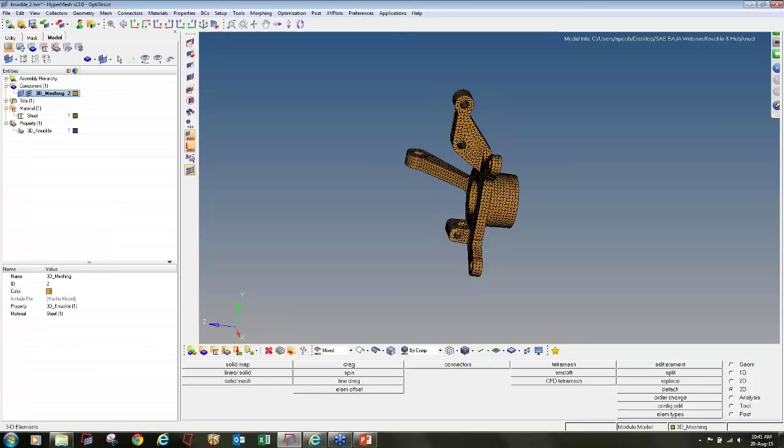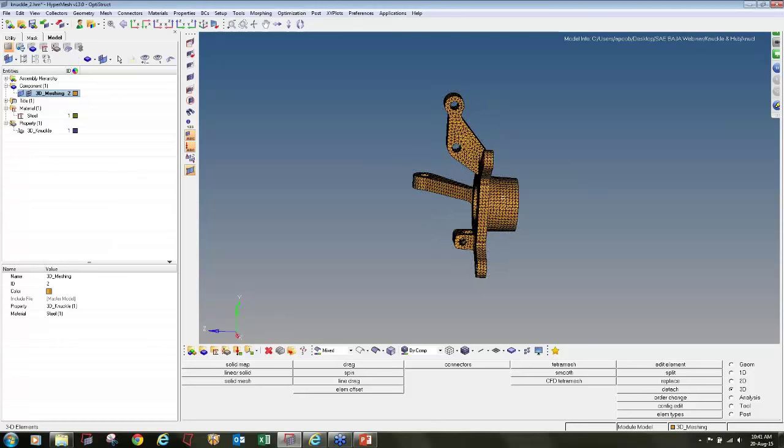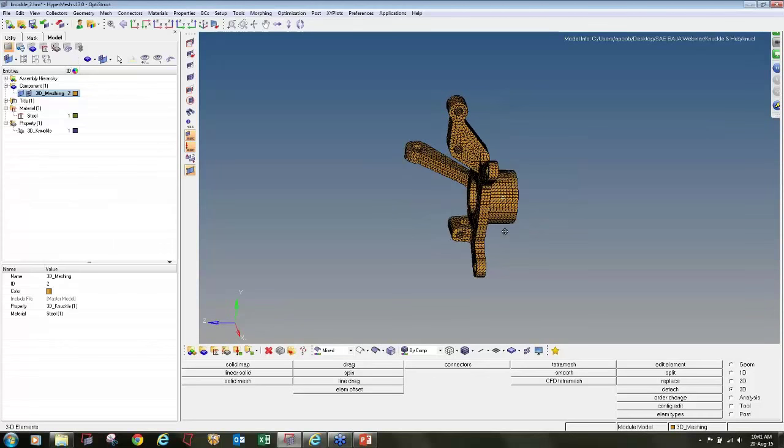One is torque, one is bending force, or sorry, braking force, and one is axial forces. So I will constrain. See, there are two ways to apply the loading conditions in the knuckle. One is from the tire side. Once you apply forces on the tire side of the knuckle, then you have to constrain the roll cage side of the knuckle.